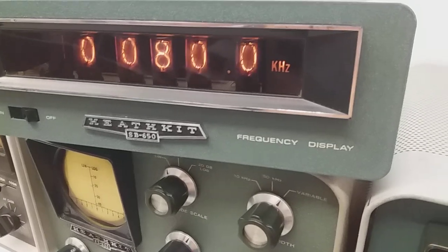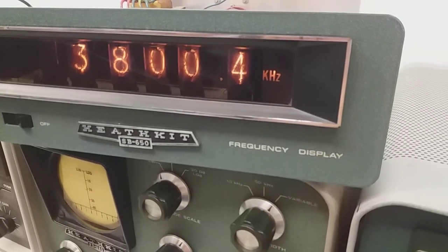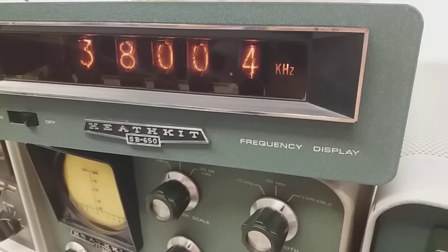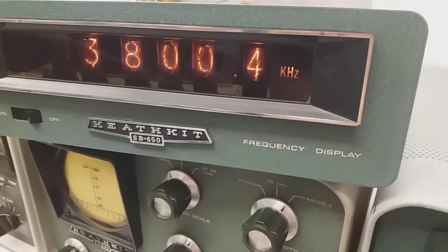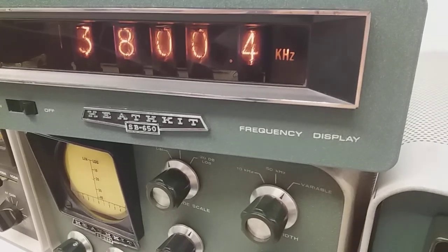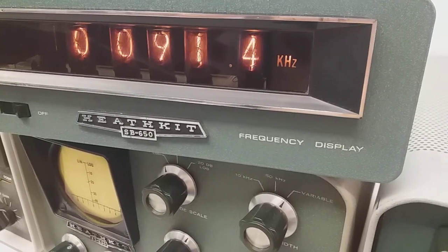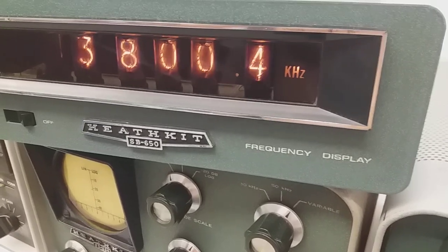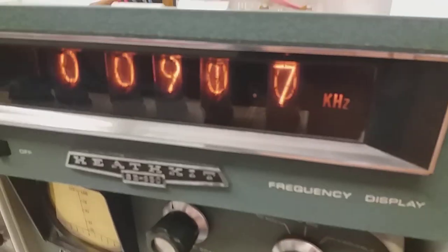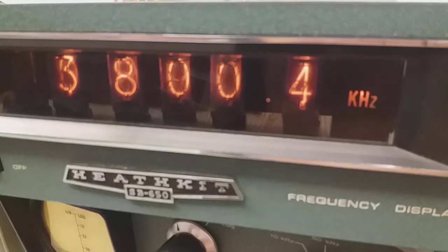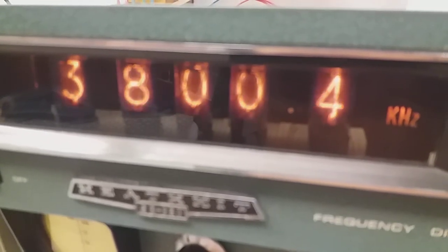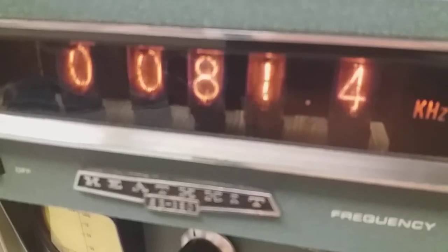Back in the shack, it turns out that I can never set the frequency below 2,400 hertz. So I think we're as close as we can. We didn't have much overhead here. By lowering the capacitance that much, we get to a point where the oscillator stops working, inside here. Another 1 megahertz crystal might help, but I don't have any of these around, so I don't know what else I can do.